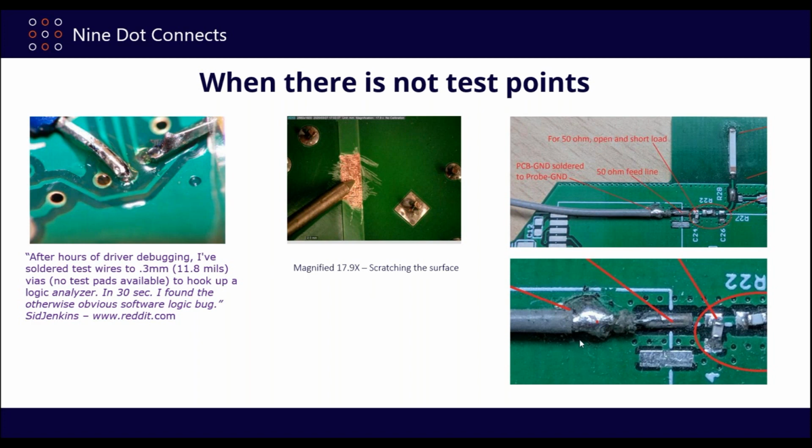And so if this, for example, already had the BNC connector or some type of SMA connector or something like that, there would not have been all this extra effort having to be put into this. They would have plugged in and they would have continued on with it. So these are some really good examples of what happens when we don't have a place to stick a probe.